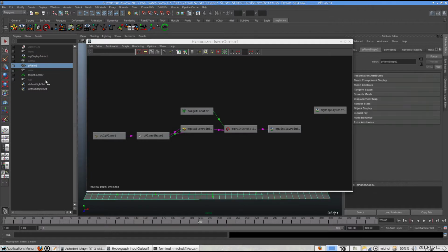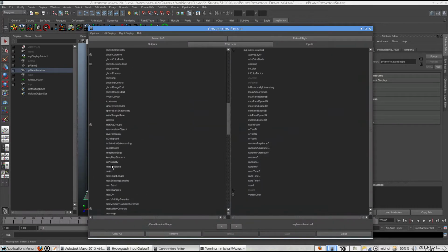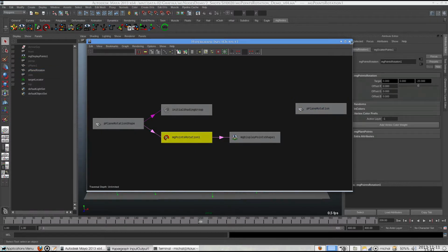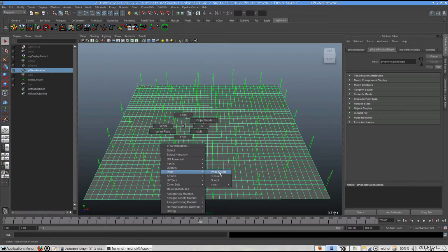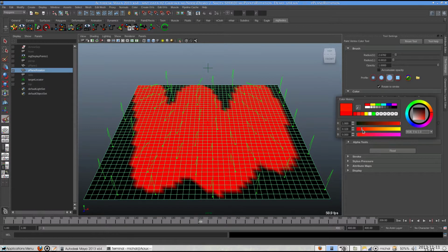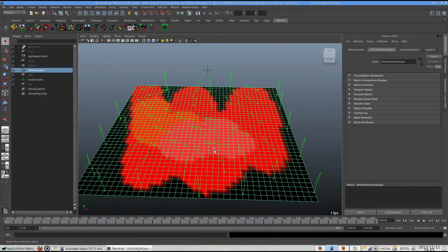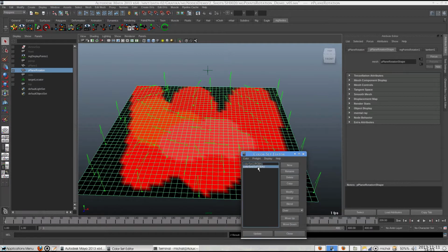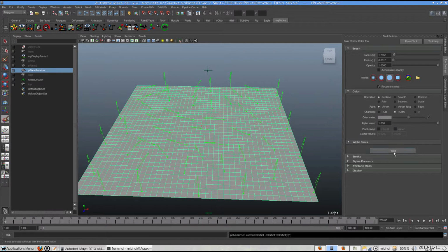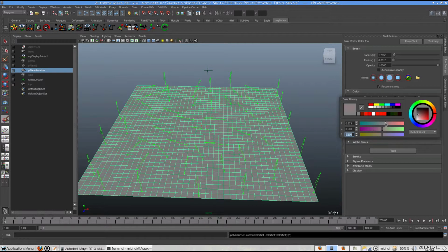Points rotation can be defined by changing vertex color values. To prevent recomputing points distribution, duplicate source mesh, connect it to mgPoints rotation node and paint rotation colors on copied mesh. In addition mode, gray does not change points rotation. Rotation modification is computed based on the difference between painted color and gray.